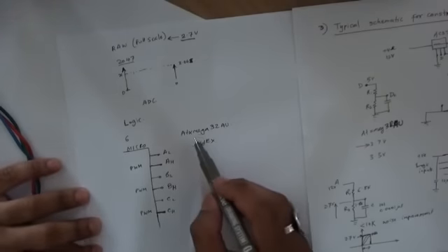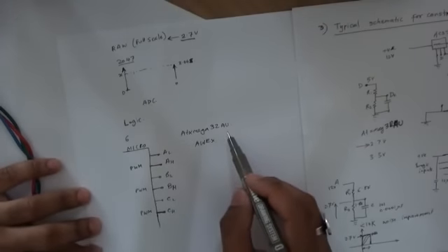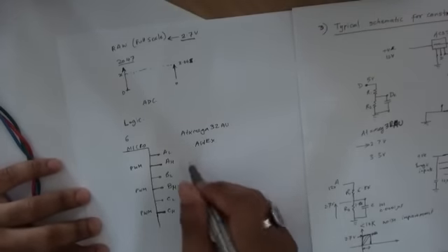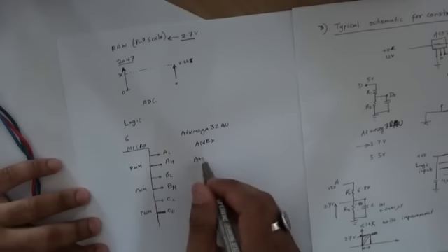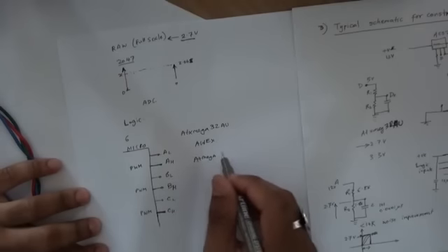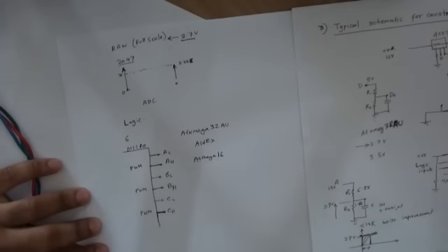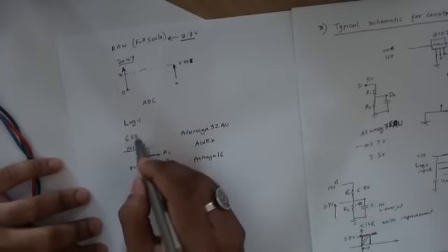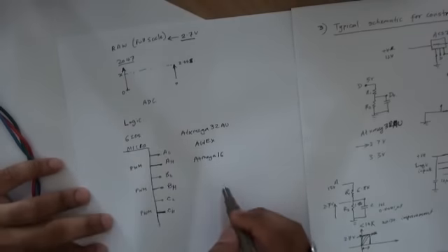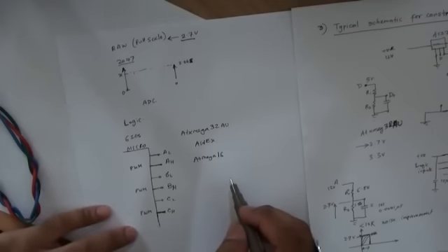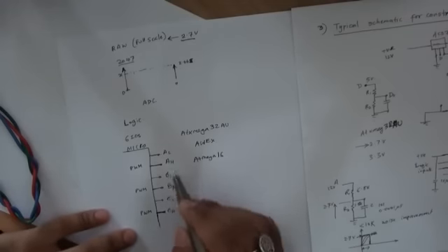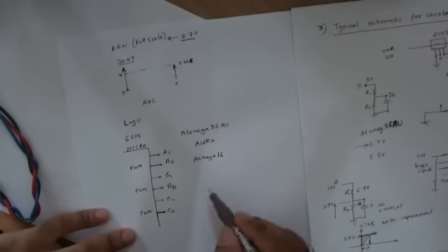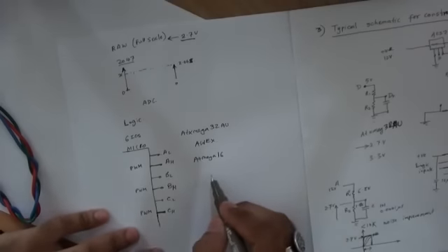If you don't use the Xmega 32 AU, let's say you used an ATmega 16 or something, then you could use any of the 6 IOs and just have the high side MOSFETs being driven by the PWM, and you can use a quad AND gate package and just use the 3 AND gates in it.